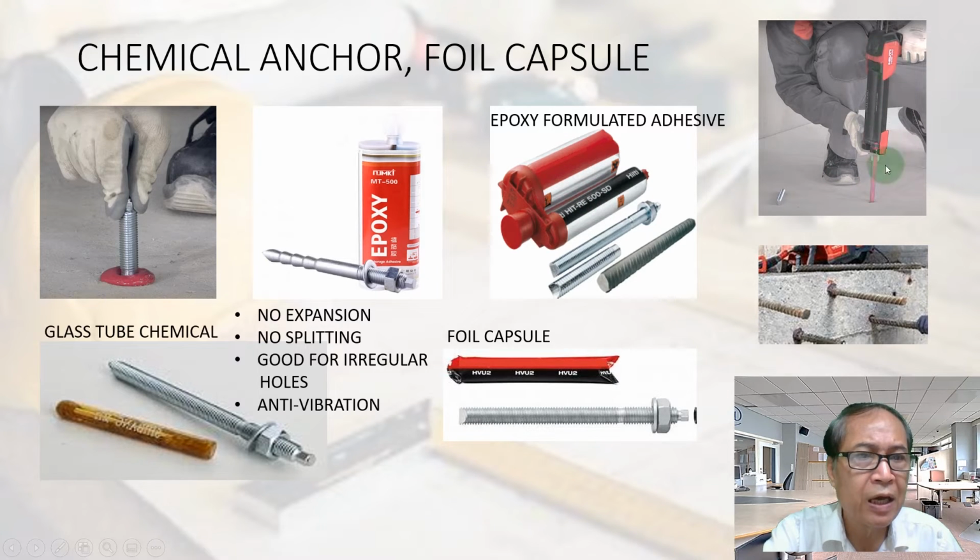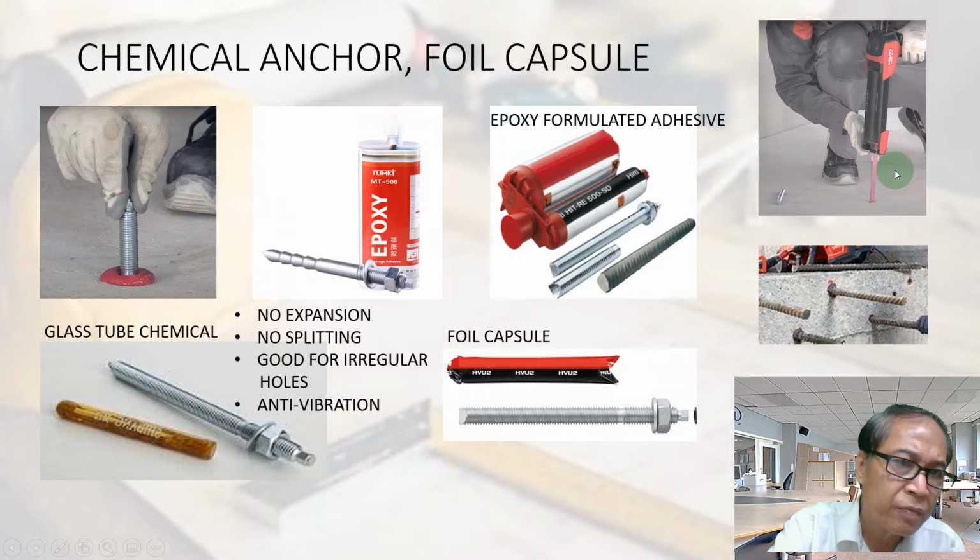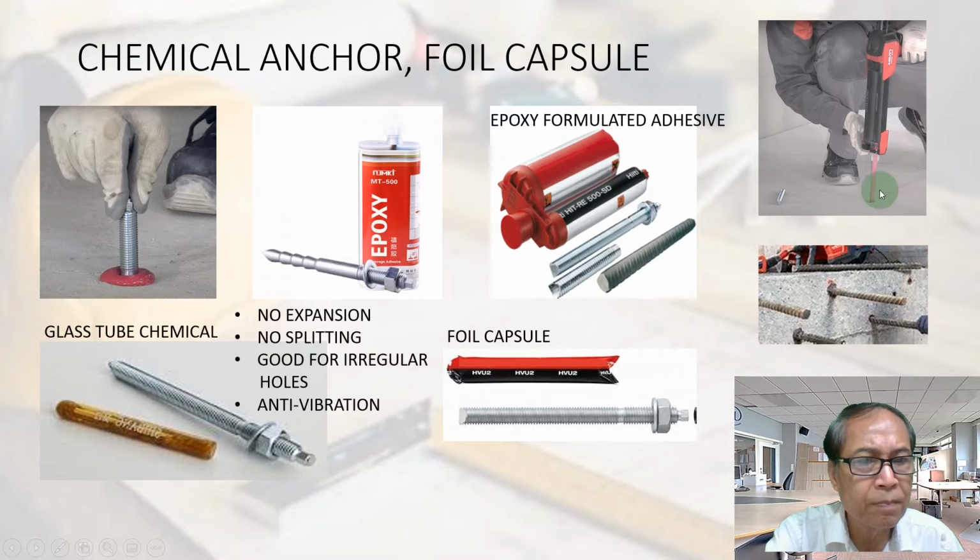We use this gun to do the injection. Then we insert the bolt in the hole. There's low expansion for this kind of anchor. No splitting because it's using adhesive. Good for irregular holes. The holes can be irregular.